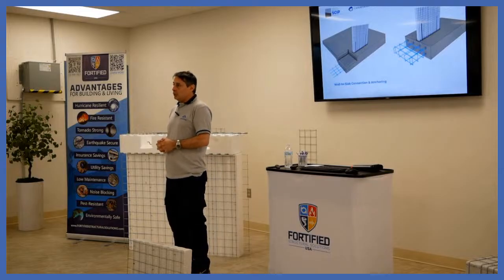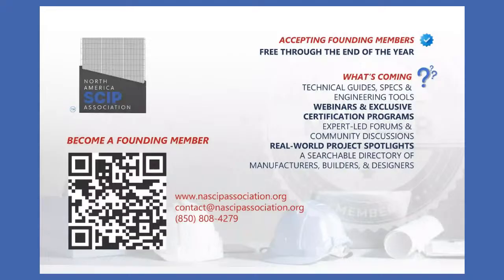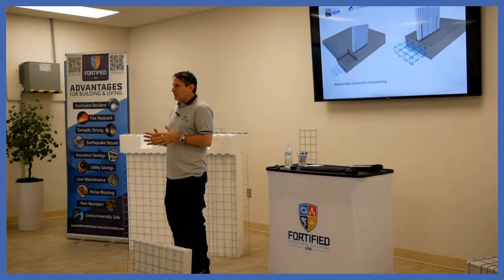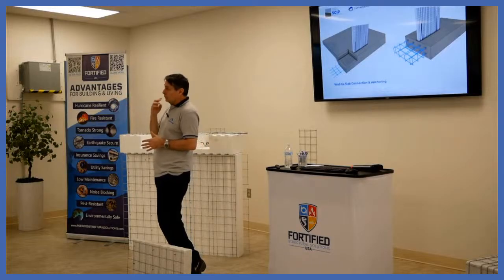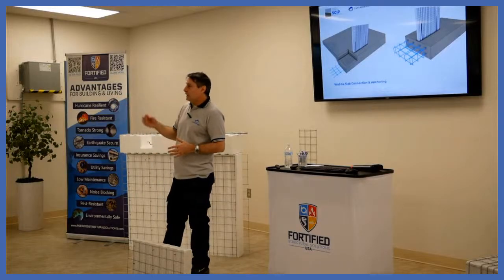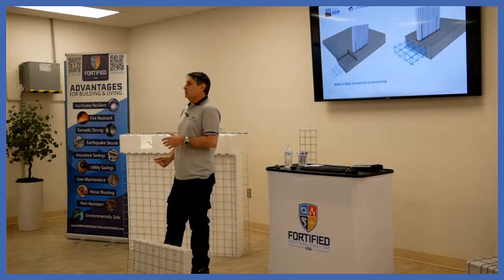And what about precast? The same. Precast is different, as forms. You can use concrete that is of higher strength than mortar, and you can also make the covering much thinner than pouring from the top, because it depends on how fluid your concrete is, the slump that you have.